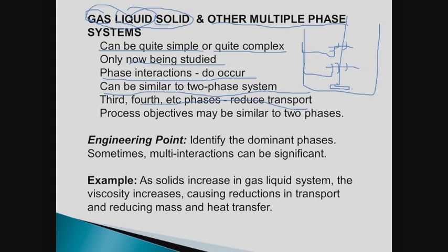With this sort of operation, the bottom impeller takes care of solid suspension. These are for gas dispersion operations and would be performing quite well. And when they are performing quite well on gas dispersion, you will also get solids.